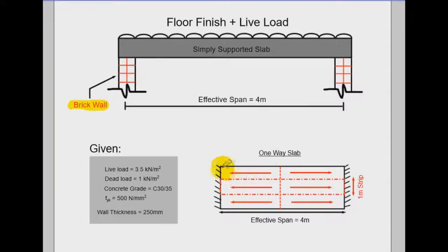And if you view it in plan view, you'll see that the notation for the simply supported condition is this one here. This is used for a simply supported slab. Since it is only supported on two sides, not on all four sides, it is immediately considered to be a one-way slab, irrespective of what kind of dimensions you have in either the transverse or longitudinal direction. That immediately makes it a one-way slab.